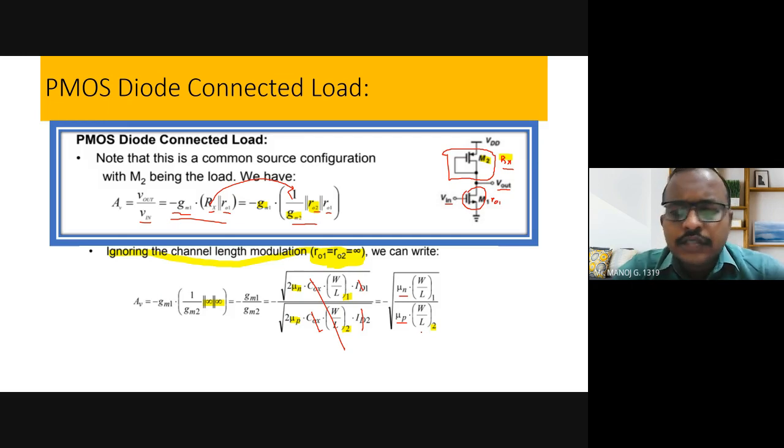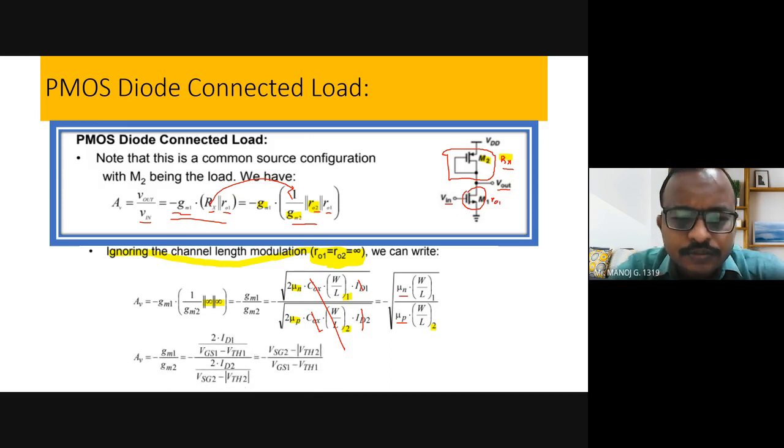Now, the last thing before we go, we have got 1 more minute. So what do we do? The last thing is the gain can otherwise be expressed as like this. This is expression wise. This is the transistor sizing. The gain can be expressed as gm is equal to I by V. All of you know the formula, right? Transconductance is I by V. We looked at last class. So which factor of I it depends is 2 times ID divided by VGS minus VTH.